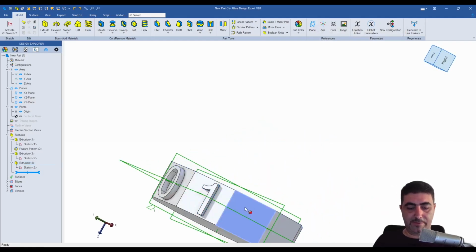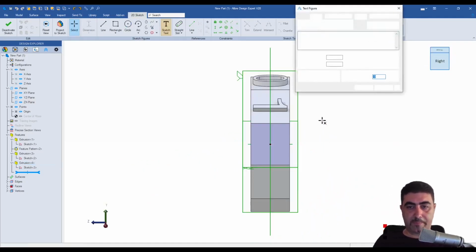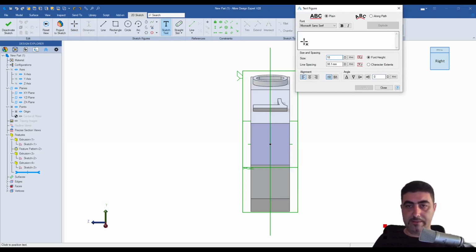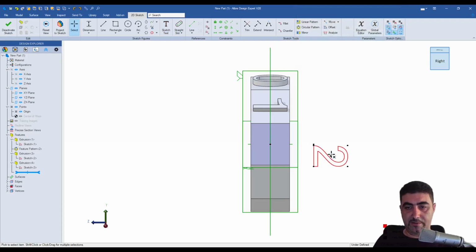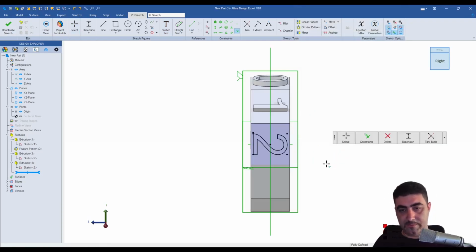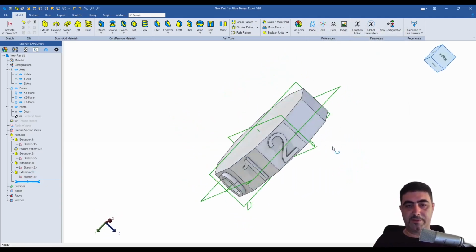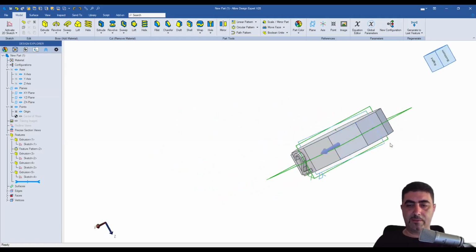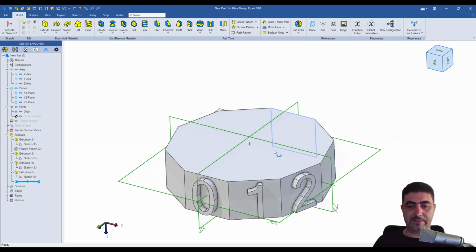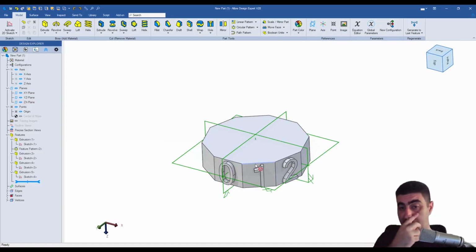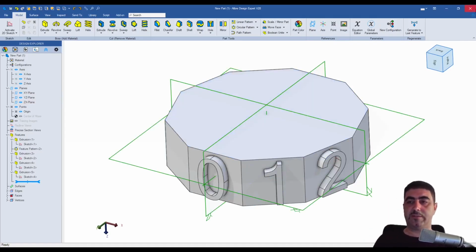Okay, let's go make number 2. So 18, number 2, I want it like this. I click here. Let's see, does that work? Works perfectly. Extrude, Control V to paste, enter, number 2 is done. And you go on and you create all of the characters that you need to be shown in your serial number, 1 on each face. So now I'm going to make like a cooking show and show you one that I've prepared earlier.